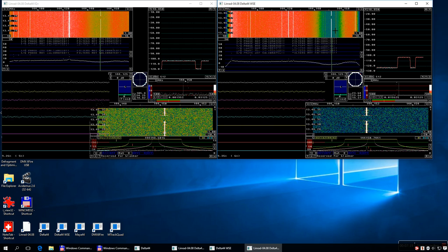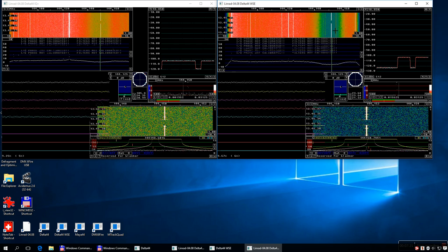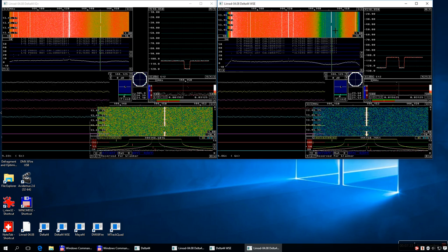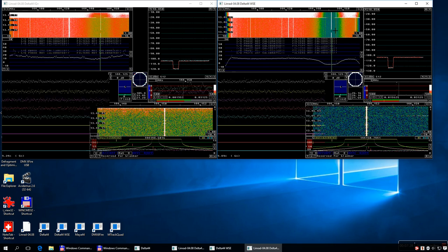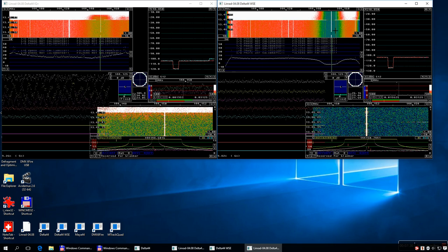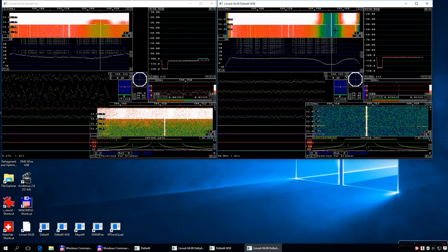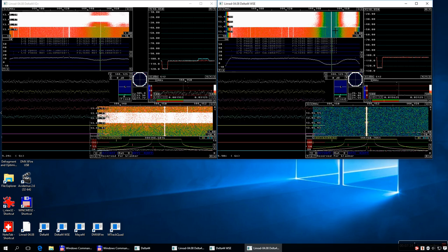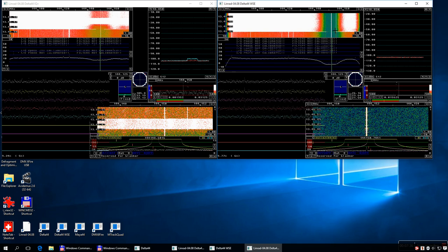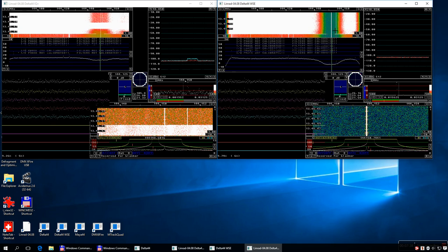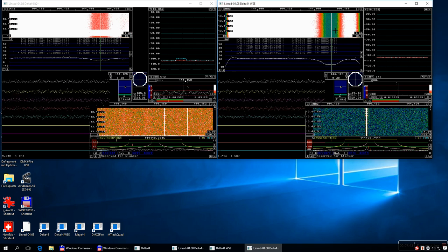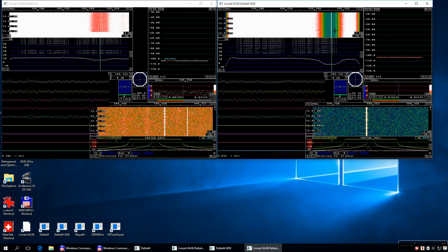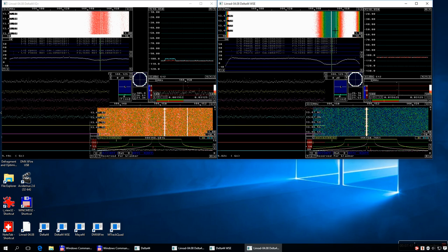And I increase the strong signal, which is now outside the visible range. Here something goes wrong in the IQ Plus. But nothing happens in the WSE, and you can see the noise floor is now lifted by reciprocal mixing a little bit more in the IQ Plus.